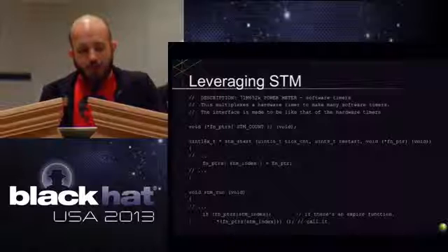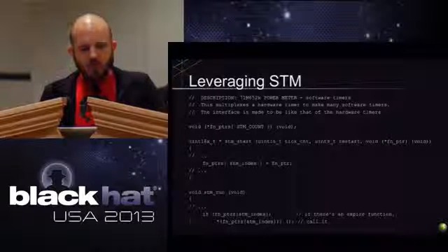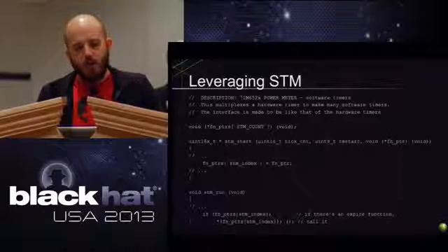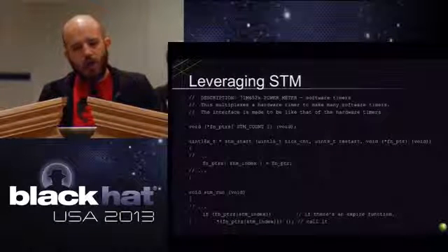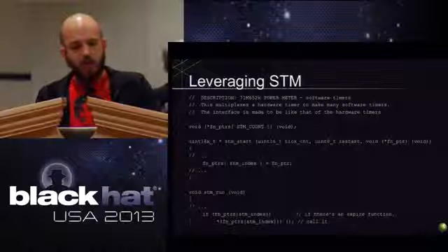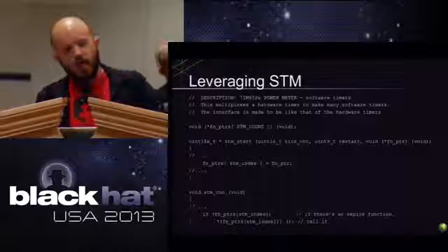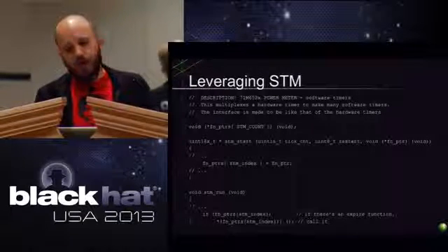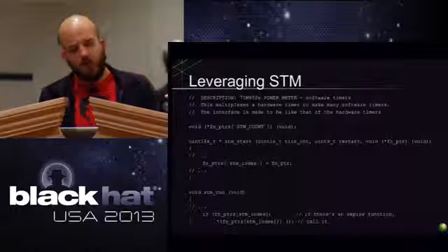Okay, so STM, how does that work? Here's what the functions look like. You can see the STM start function is just taking a function pointer and how many counts you want, and then it stuffs that onto the fn_ptrs array. Later there's another function that says, if one of these has expired, then let's go ahead and call it.